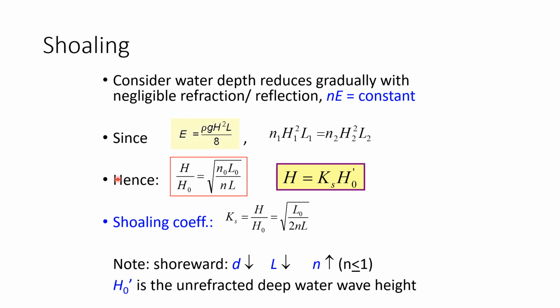Okay, now if we write the entire right hand side, it looks like this actually. Why? On the right hand side, N0 is the ratio of the group wave celerity compared to the individual wave celerity, and in deep water N0 equals 1/2. So the right hand side can actually be written in this form, whereby N0 is changed to 1/2.